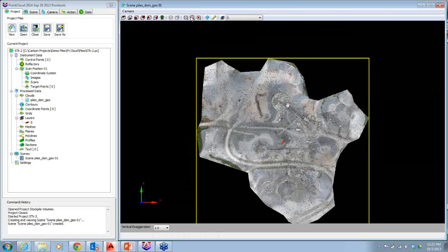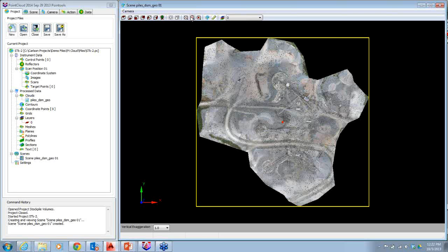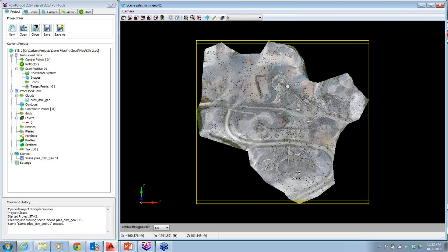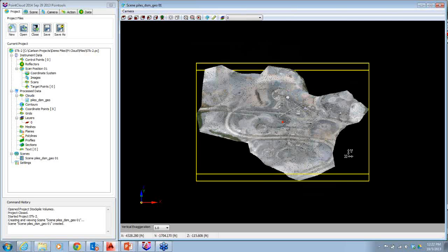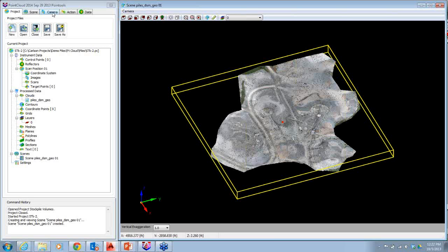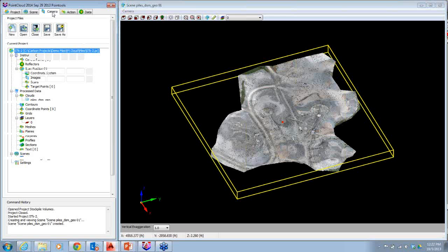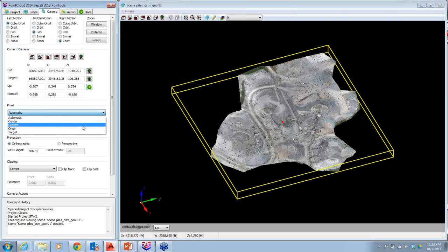And now I'm going to move this. You can see the blue key. And if you move your cursor where I have an XY down here, you'll see a Z that allows you to turn it. And the red dot is the center position of the map. If you do want to change the center position, you can go to camera here, go down to custom, and just pick this little dot here. And with the control key down, it says control click. I'm going to pick the beginning of this Hall Road. There, the red dots changed there.